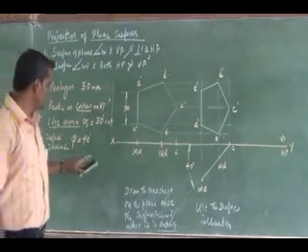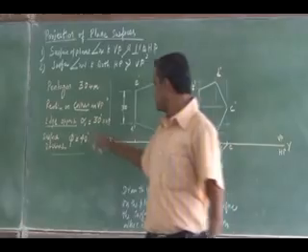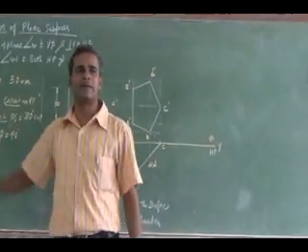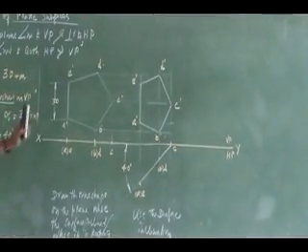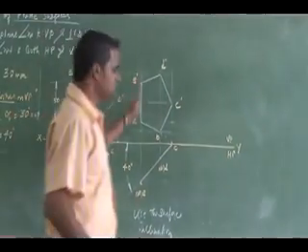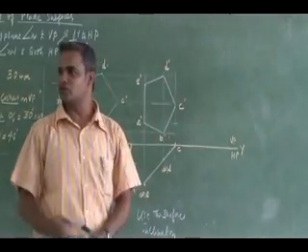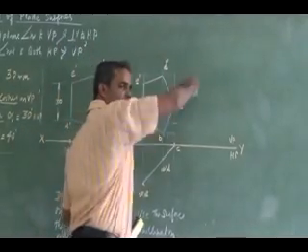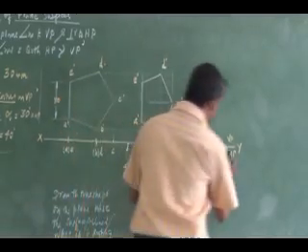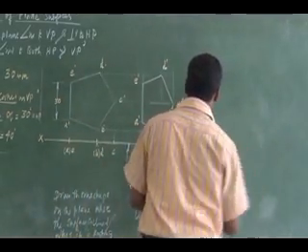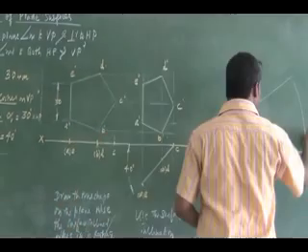Now, use the third step, use the apparent inclination. So what is apparent inclination? Alpha. Why am I saying it is apparent inclination? Here, the surface is not at 30 degrees to HP. Only this edge appears to be inclined at 30 degrees. That's why it is apparent. I just have to reproduce it tilted in a 30 degree manner, right? So you draw a 30 degree line for this.